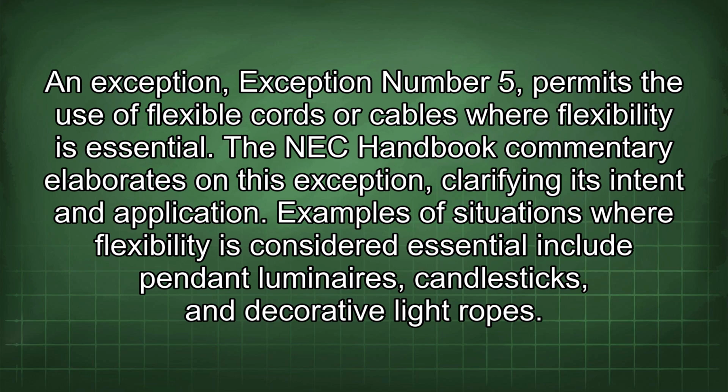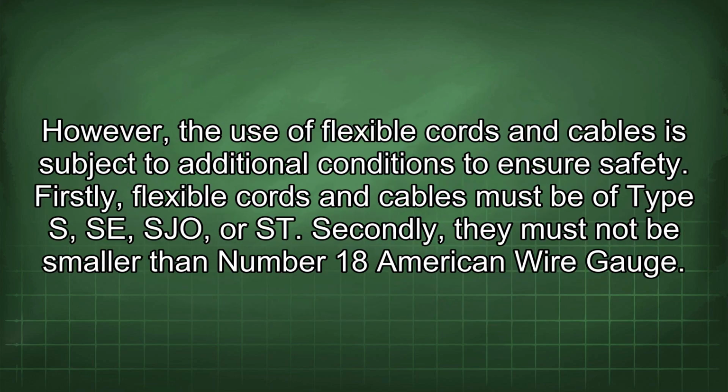An exception number 5 permits the use of flexible cords or cables where flexibility is essential. The NEC Handbook commentary elaborates on this exception, clarifying its intent and application. Examples of situations where flexibility is considered essential include pendant luminaires, candlesticks, and decorative light ropes. However, the use of flexible cords and cables is subject to additional conditions to ensure safety.